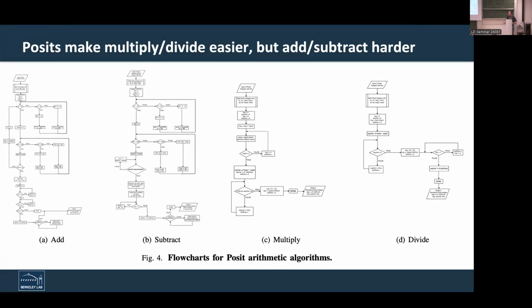Yeah, that's true. I would say that transistors are cheap, but every one of these branches that I take here requires an extra clock cycle. And so I have a really complicated pipelining challenge here. So the transistors are cheap. It's not about the transistors, it's about the microarchitecture. To meet timing, I have to have a lot of buffering, because a long flow chart requires a buffer between each of these stages, and a short flow chart doesn't require as much buffering. So meeting timing is a challenge.